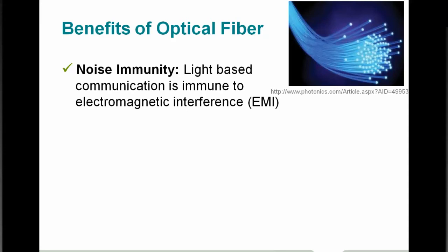Since we're not using electrical signals and we're utilizing light, having somebody with an arc welder nearby is not going to impact what's traveling on the fiber optic cable. So this inherent noise immunity is huge, and is really helpful in some of these more difficult industrial applications.